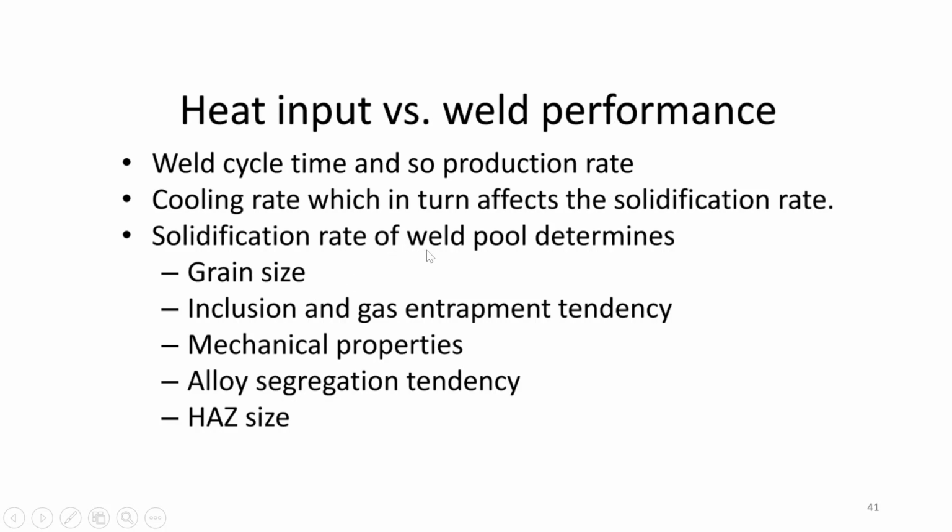So the solidification rate of the weld pool determines grain size, inclusion and gas entrapment. So if the solidification rate is higher, then more gases will be entrapped because they won't have time to escape from the weld pool. Okay, and inclusions will also be higher.